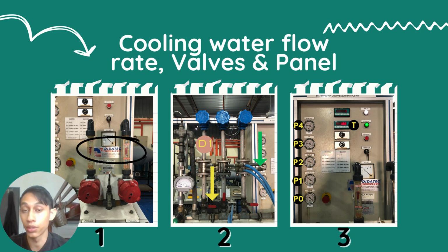Next, in picture number 2, the blue flexible cable, shown by the green arrow, was plugged into diaphragm D1 with compressing air at P4 equal to 1.5 bar absolute pressure. When that's done, the main switch on the control panel was turned on and the small red lever, shown by the yellow arrow, was turned in order for the air pressure to enter.